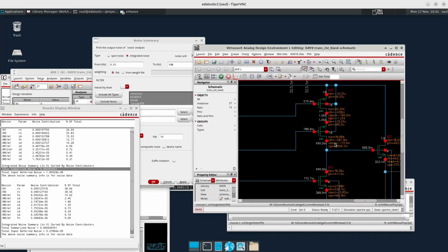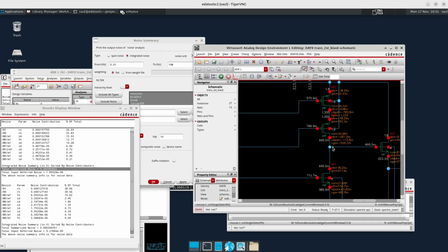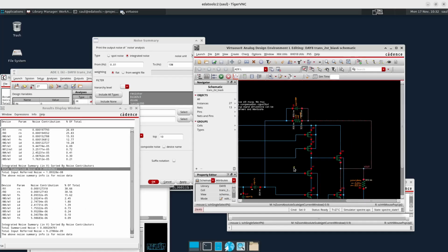So this is, as I mentioned before, due to the capacitances to the substrate, this noise current of the cascode starts to kick in at higher frequencies. But at low frequencies they really don't contribute much noise. Something to think about, because that might affect the way that we think of the sizing of these transistors. The size of the transistor will affect this capacitance to the substrate.